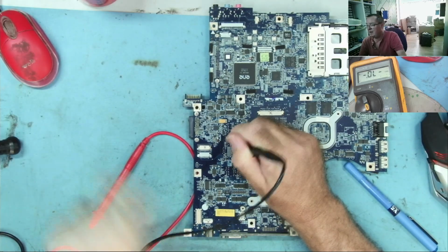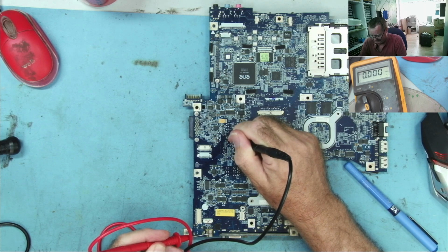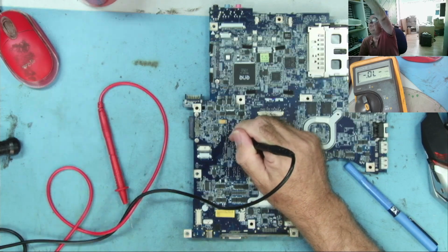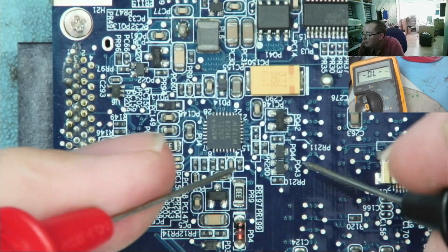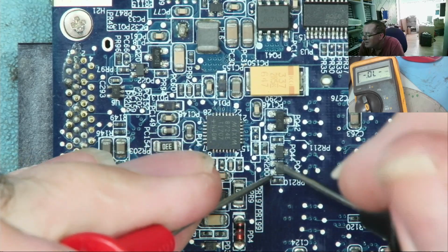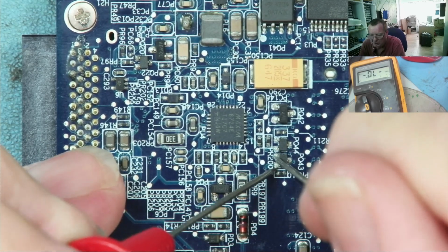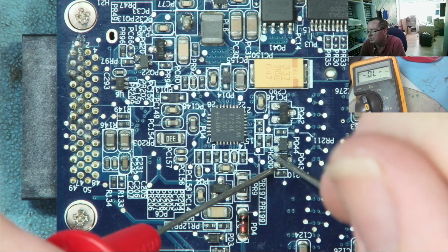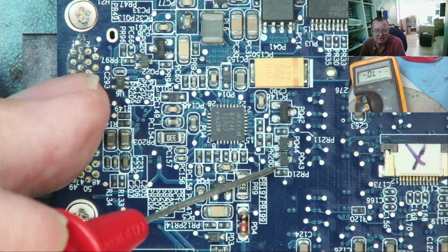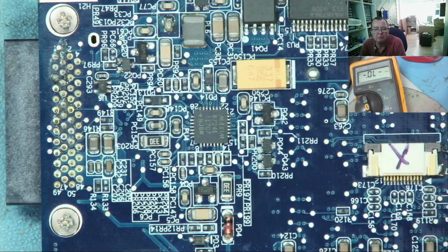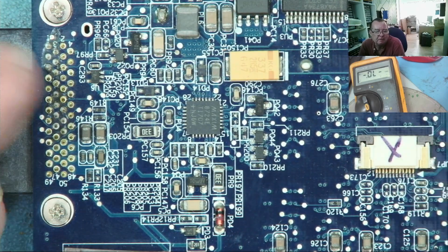So I can say, okay, is this pin connecting to ground, the metalwork? Yes, it is. So I know straight away that I put a positive lead, my red lead, on here to here, and I see that diode junction. That polarity will not occur during normal operation because this board has a positive supply. So the ground can never be positive with respect to this gate. So that diode that we see will never conduct, not in the operation of this circuit.